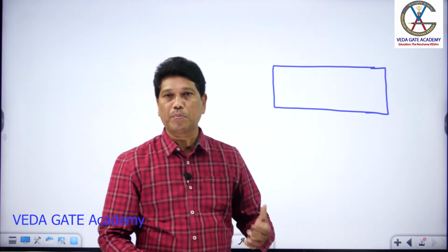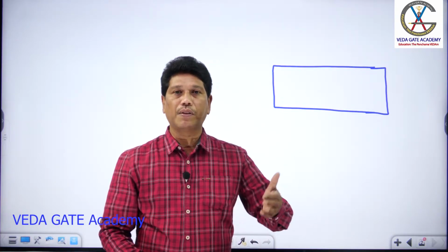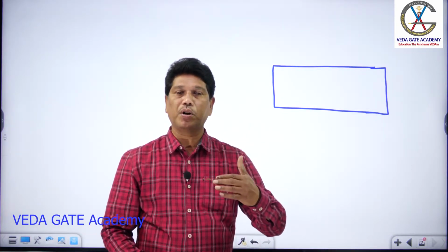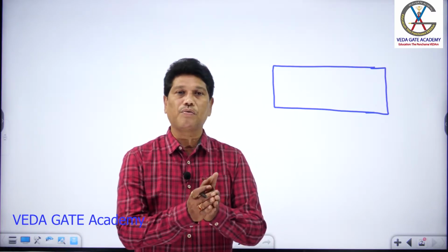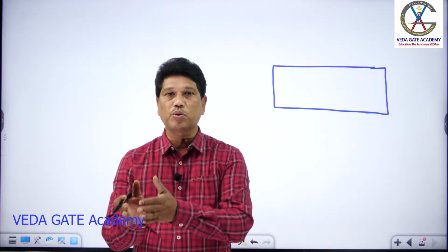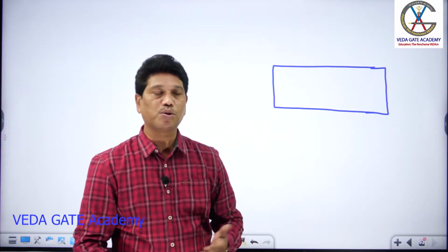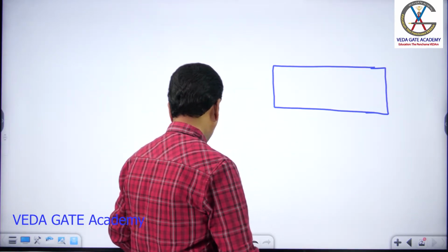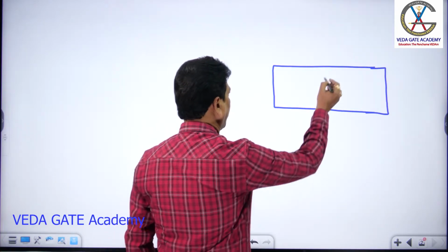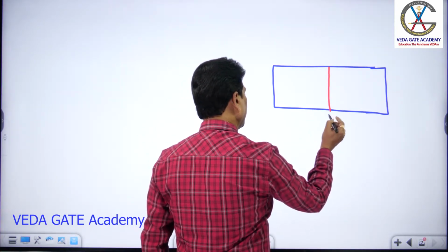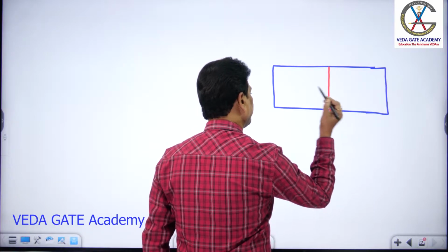So I take one type of crystal, N-type or P-type, and on that I keep the opposite crystal, and then I heat that to a high temperature. Then automatically you find that one crystal is diffused over the other, and that contact surface is called a junction, you know, right? A junction is a contact surface between P-type and N-type materials. This is called a junction.